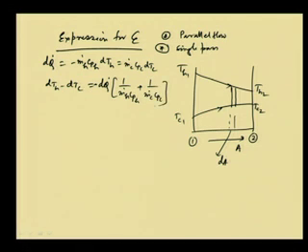Okay. And again we know that dq dot can also be written as U dA. This is for dq, the differential amount of heat transfer happening for the area dA. So, it will be U, the overall heat transfer coefficient, into dA, the differential area, into the temperature difference. If in this region the temperature of the hot fluid is Th, and in this region the average temperature of the cold fluid is Tc, then it will be U dA into Th minus Tc. So, this is the temperature difference.